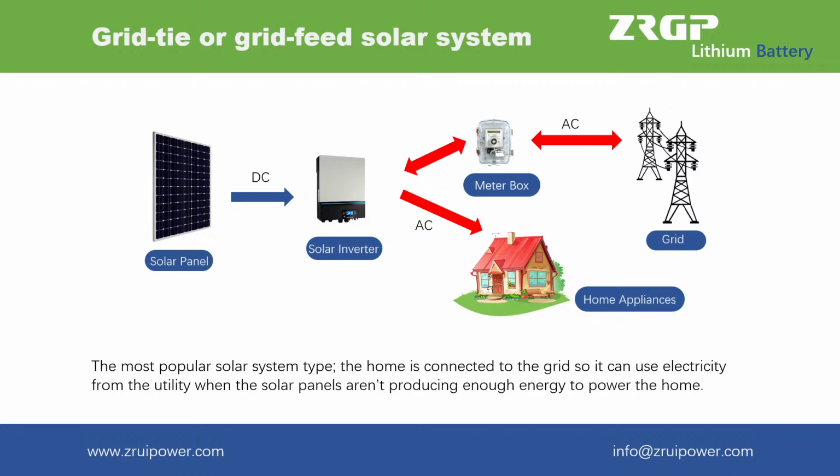Unlike hybrid systems, on-grid solar systems are not able to function or generate electricity during a blackout due to safety reasons. Since blackouts usually occur when the electricity grid is damaged, if the solar inverter was still feeding electricity into a damaged grid, it would risk the safety of the people repairing the faults in the network.